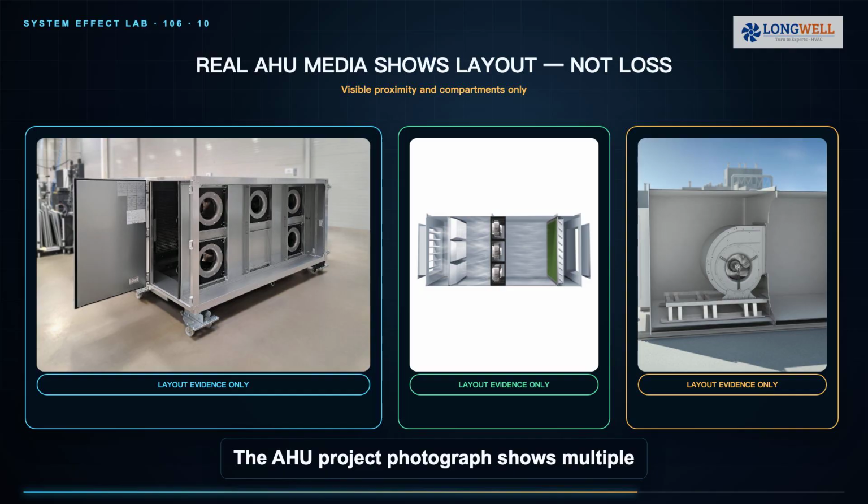The AHU project photograph shows multiple plug fans inside a real air handling enclosure. It establishes the physical proximity of fan openings, compartments, coils, panels, and service space. The fan wall and retrofit images illustrate different flow-out concepts. None of these images measures a system effect loss or proves that one arrangement is superior without matched test data.